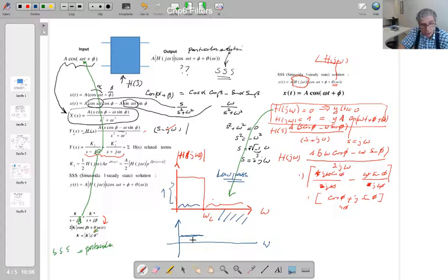If there is a different delay for different frequencies, you confuse the signal that you're going to get. Your feeling is not going to be a proper feeling, because the different delays at different frequencies change your understanding of the signal. Let's say this signal is transferred to a voice, so this voice is going to be a problematic voice. So the change of the angle of H(j omega) is critical as well in terms of group delay.